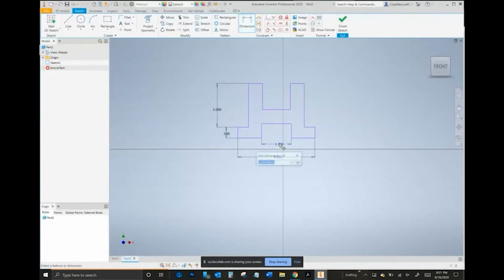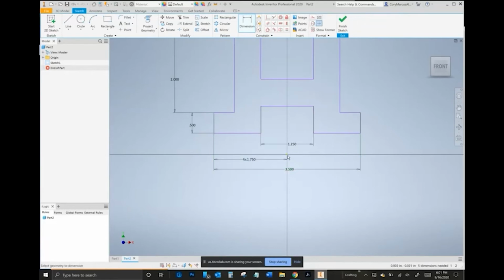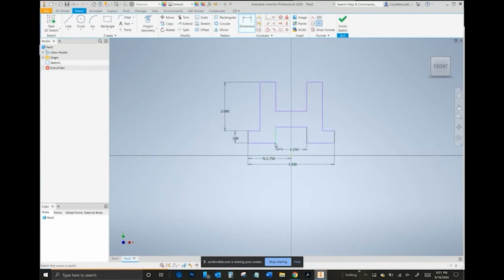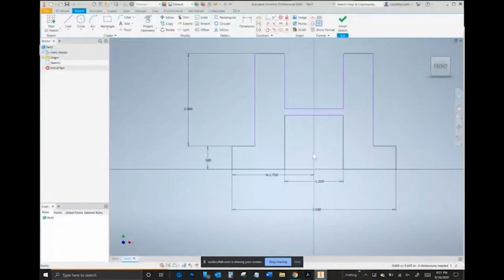1.25 between these two. I'm going to locate this drawing horizontally, saying it's centered. From here to here is half of this. And then I'm actually just going to say that this line touches this point. That way, it looks like it would be some kind of mounting pattern, so having a plane at the bottom might help.